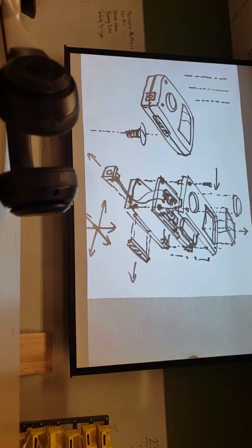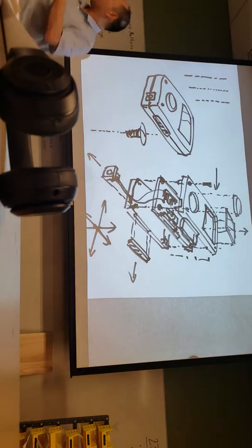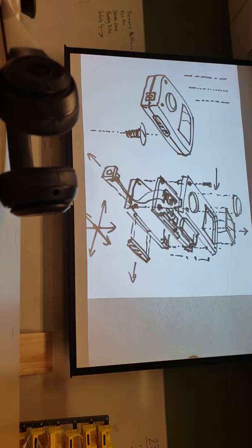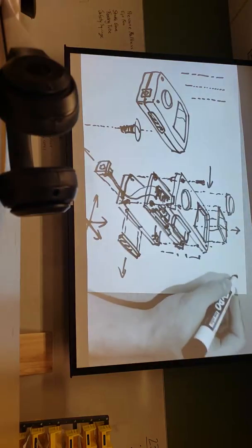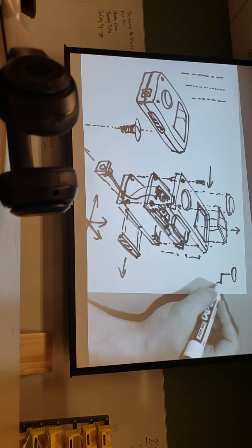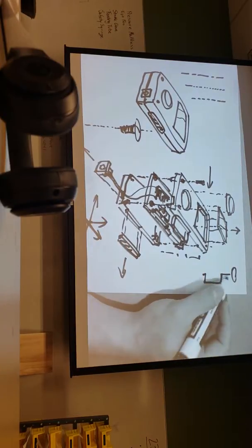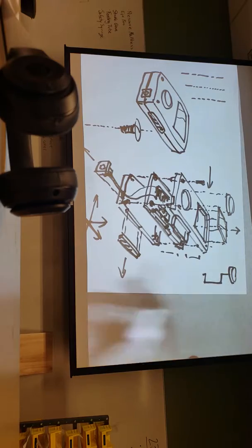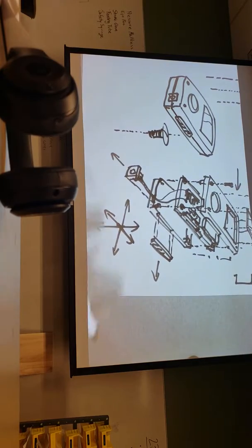And so what I would encourage you to do is always think linearly in terms of the paths of your parts, if you can. Sometimes parts will have to do some funky stuff where it goes in straight, but then needs to go to the right and fit in. But I would say try not to get into the weeds with this kind of complex movement, and try to break it down to just your major directions, axes of direction.